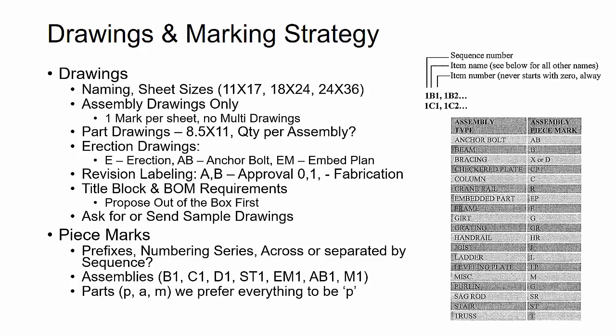It gets really bad if you've already started making your shop drawings, because if you have to go back and affect your numbering and piece marking, you're going to have lots of marks changing on you and drawings being revised, and you don't want that. So it's super important to understand exactly how the piece marking is going to work on a job at the early stages, understand the prefixing system, whether or not the sequence or the phase number needs to be in the mark, and then coordinate with your Tekla or SDS2 administrator to figure out exactly how they need to set up the job so that you get the right piece marking.